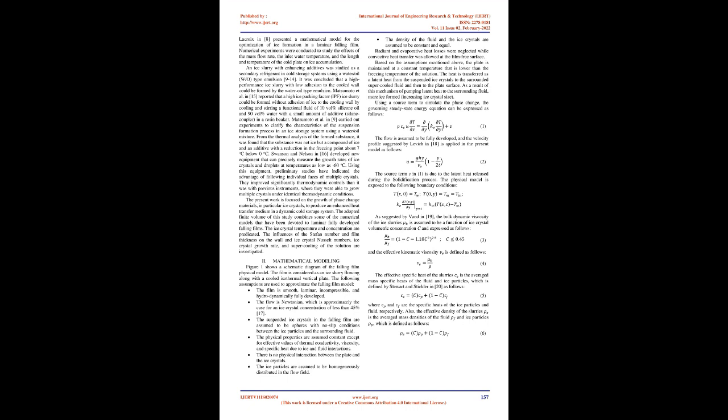Matsumoto et al. [15] reported that a high ice packing factor, IPF, ice slurry could be formed without adhesion of ice to the cooling wall by cooling and stirring a functional fluid of 10 vol% silicone oil and 90 vol% water with a small amount of additive, silane coupler, in a resin beaker. Matsumoto et al. [9] carried out experiments to clarify the characteristics of the suspension formation process in an